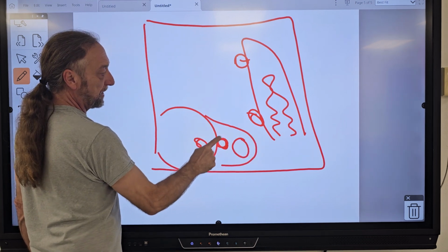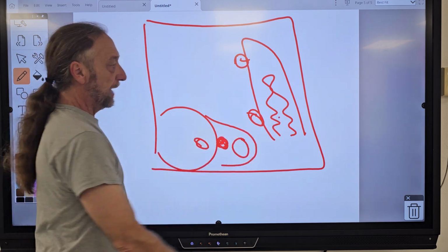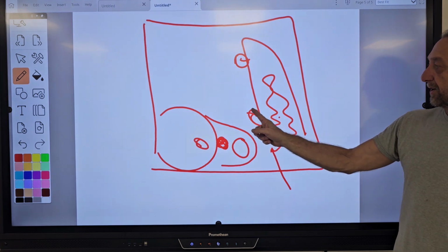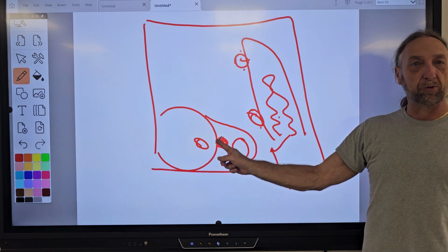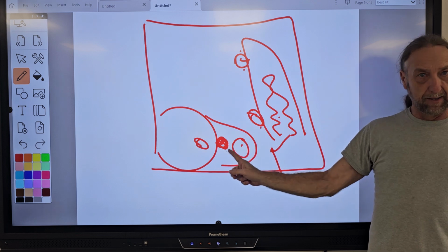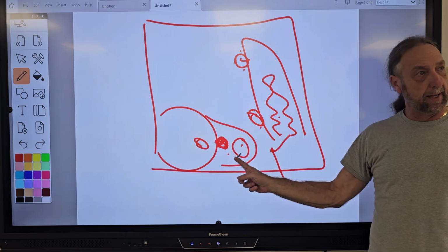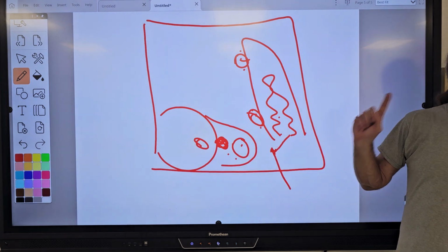So you have a thermostat right here, not there. You have 1, 2, 3, 4 parts right there. You put your meter lead on one of these terminals and you touch here, here, here, and just keep going back across till you find out, oh, I have voltage here, but I don't have voltage on here. That's the problem. If it's good, I have voltage here and here. But I'm always leaving one meter lead at that one point.